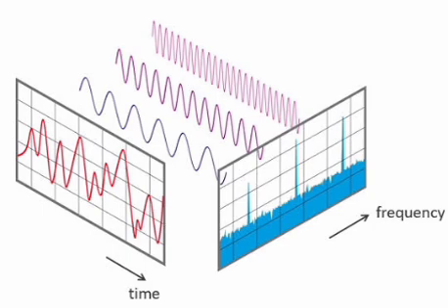The infinite impulse response of IIR filters continues indefinitely. The difference equation is given as y of n equal to 1 by a naught, sigma i equal 0 to p, bi x of n minus i, minus sigma j equal to 1 to q, aj y of n minus j. P means feed forward filter order, q means feedback filter order, bi means feed forward filter coefficients, ai means feedback filter coefficients.